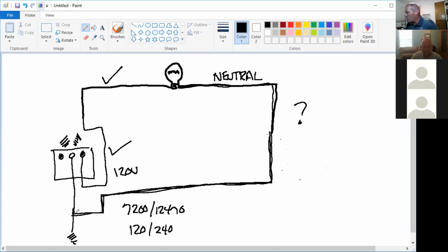Neutral. The neutral. There you go. It's the neutral. And in an electrical system, we take the neutral and we ground it. Well, how do we ground it? We'll come down the pole with a pole ground attached to it, or we'll go down to a ground rod that's in the earth. So here's the things that I want you to get out of it.